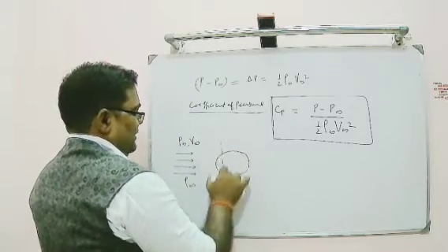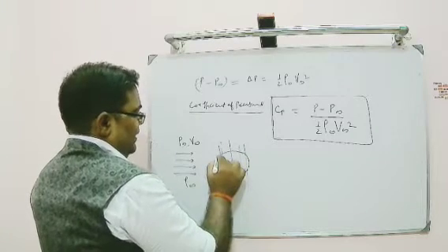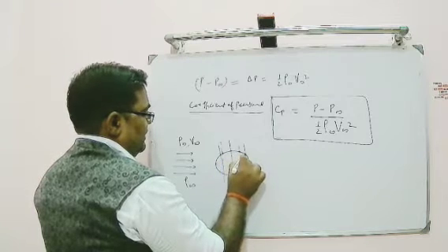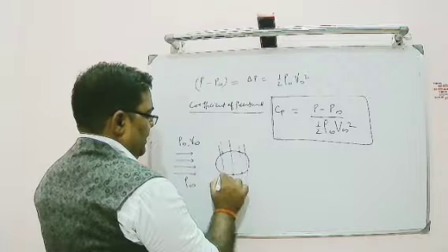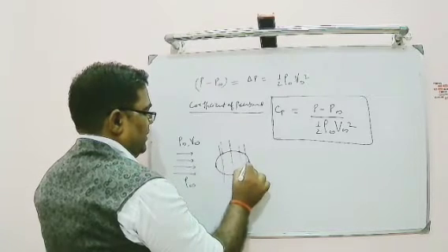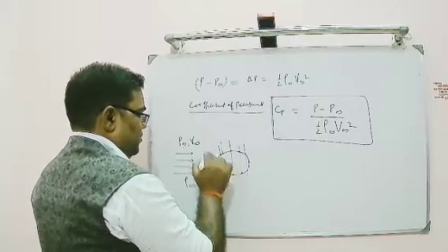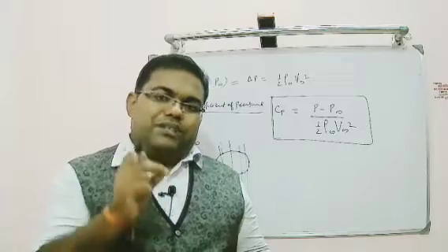So if we divide like this, like this, like this, for the sake of explanation, we'll get these kinds of points over the entire surface, bottom and top. At the same symmetrical location you will have a point. One point you can put here, one point you can put here, or in between also you can put some points, right? At these points we'll put the static pressure ports.